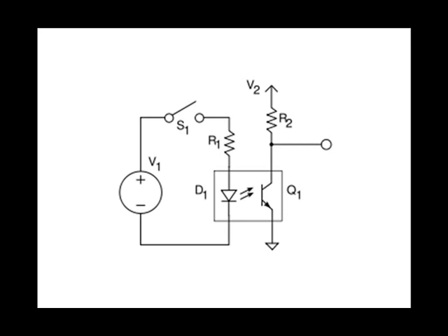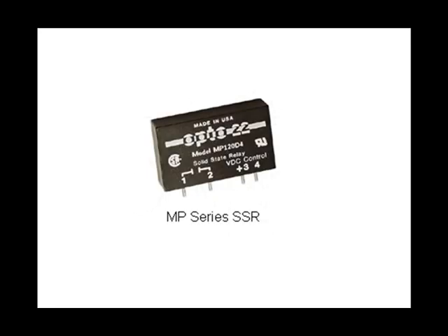Aside from the fact that this manufacturer has their pins numbered differently than my optical isolator, in other words, pins 3 and 4 represent the LED and pins 1 and 2 represent the normally open contact or the output.